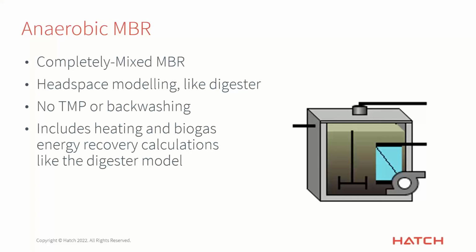So it's a completely mixed MBR. You'll notice it does not have any bubbles in it because, of course, it's not aerated. So it's anaerobic only, with headspace modeling just like a digester. That's why you see there's a lid on it here and that we have our gas connection point like we do for the digester. The TMP and backwashing is not present in this model. We don't have that extra set of calculations in here.